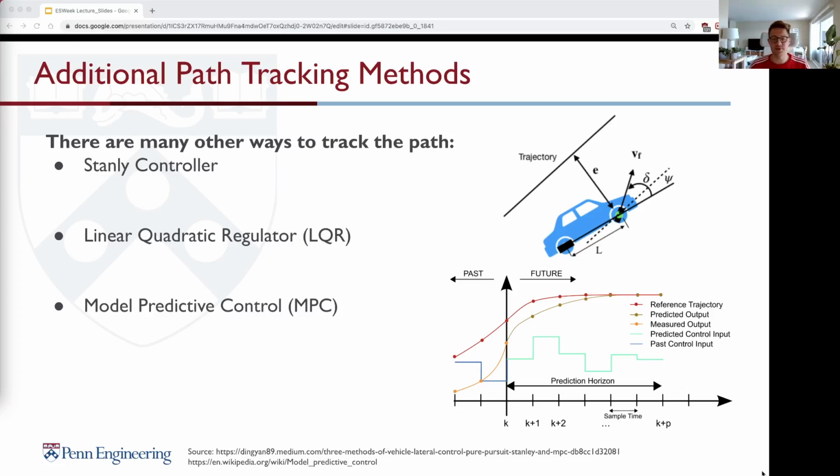Both of them have the possibility to integrate the vehicle dynamics, which means you can do with both of these algorithms a very accurate steering while taking care of the vehicle dynamic behavior of the car. The disadvantage of these algorithms, they are computationally heavy and need some expertise in setting up the optimization problem and creating the code afterwards, and finally the tuning of the algorithms.